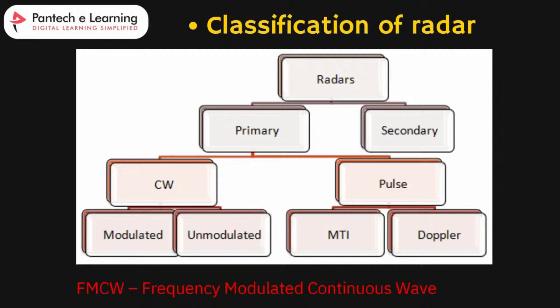One more, this one is the FMCW, which means frequency modulated continuous wave. This radar emits a continuous wave with a frequency that continuously changes over time. FMCW is mainly used for automotive applications, and it emits a signal with continuously changing frequency over a defined frequency range.